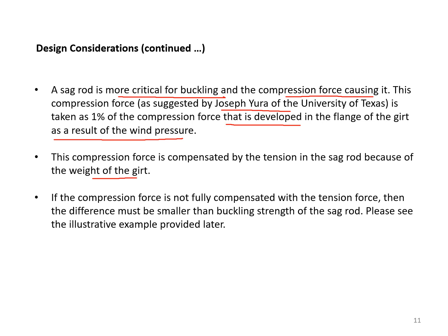If the compression force is not fully compensated with the tension force, then the difference must be smaller than the buckling strength of the sag rod. And we'll have this again coming up a little bit later in an example problem.